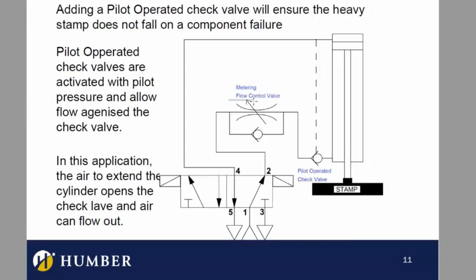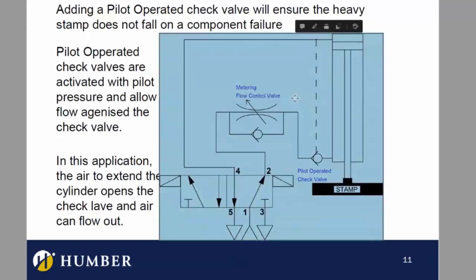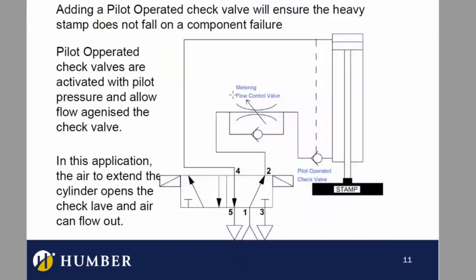This is not a pressure control valve. It's just a throttle valve, which is kind of weird because you think it's very much like a resistor. And we know that there's pressure loss on either side of a resistor, or there's voltage loss. But the pressure drop on either side of this is significantly small compared to the pressure that's operating this.